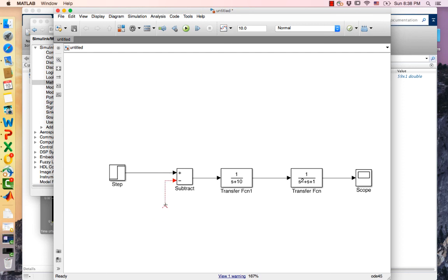If you see here, drag the line from here, then you do here. You try to go up. If you try to pick some signal from here, you don't automatically pick it up. But what I found out is, if you try to start from something here, you actually cannot start the line. So you want to start from something that connects, just like what I did here. You select from here, and then I go in this direction. You try to draw some lines, and I go backward, go top. Then I can pick up the signal. The lines you can drag left or right to make this look nicer, or whatever you want to do to make yourself comfortable.